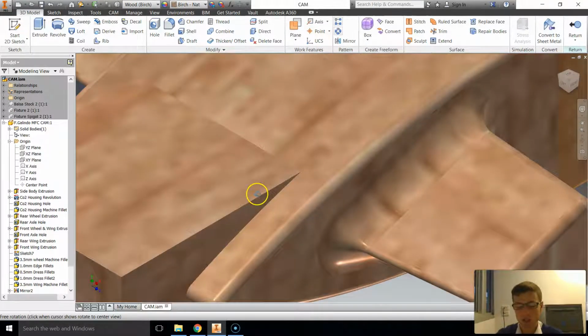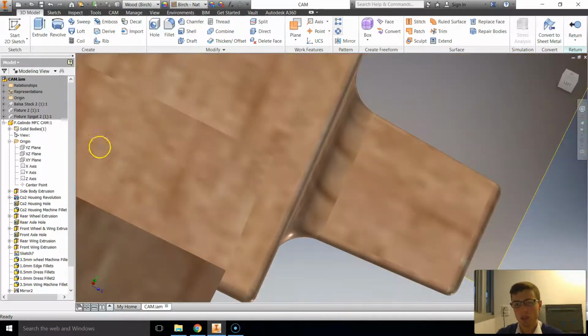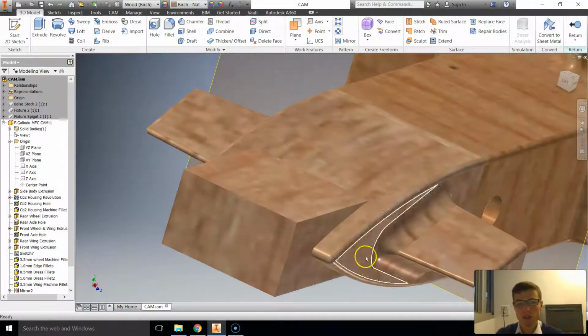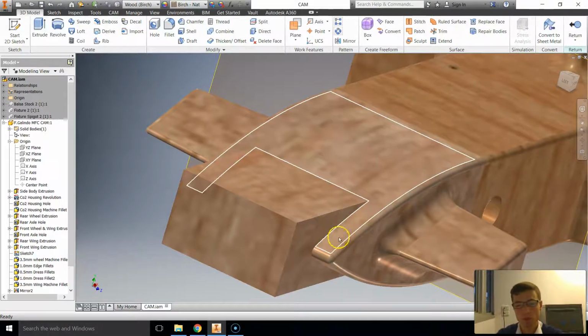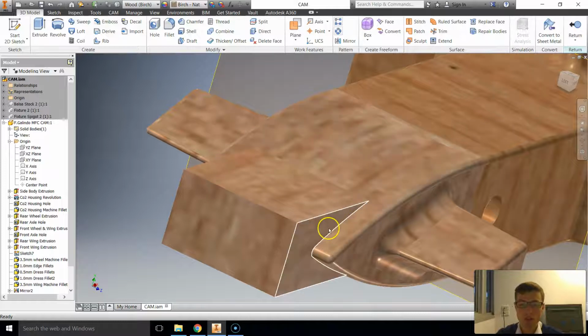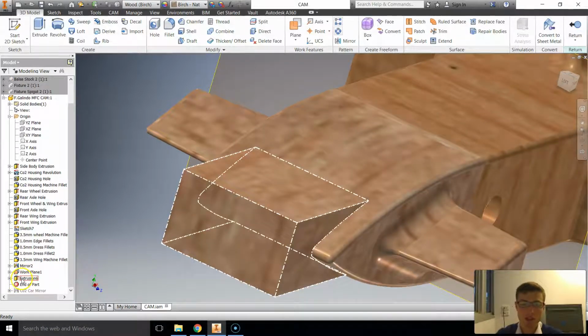Now one of the interesting things about this is that you'll notice there's a very small amount of space there, and when you machine, obviously the machine's going to be, as we've talked about, a bullnose mill bit, so it's probably going to leave a fillet. Well, it will leave a fillet there, and if the fillet's too big, you won't know the actual edge surface. So looking at this, I actually kind of think it's a bit small.